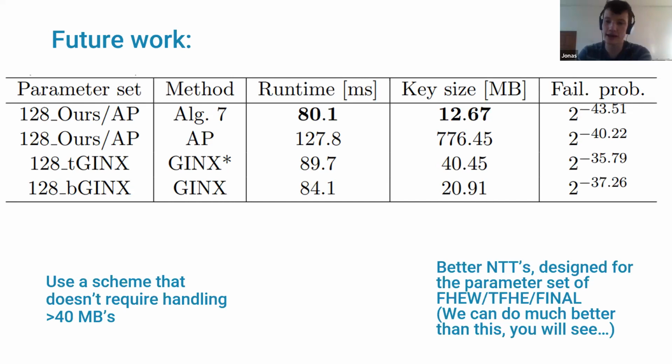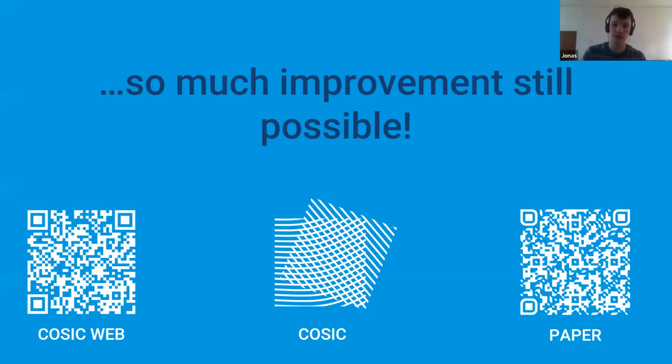Merz et al.'s design has certain interesting properties that allow it to be very flexible. But for fully homomorphic encryption, you don't quite need that flexibility, especially not for the 3rd generation schemes. So you can significantly improve the throughput per area over even the best NTT design, which is what Merz et al.'s design was in 2021. So there's still a lot of improvement possible.